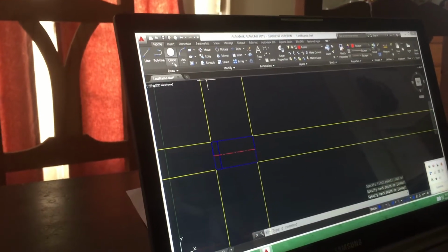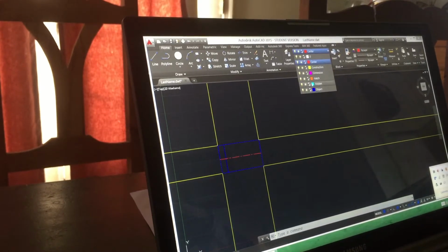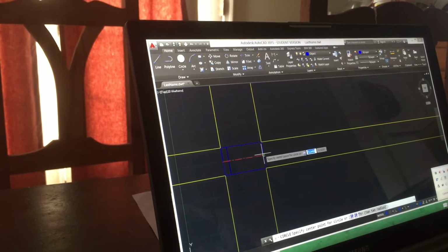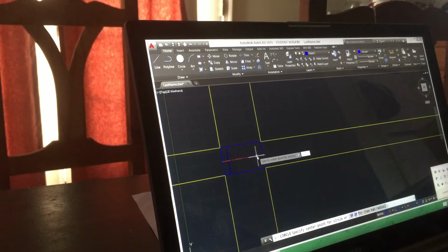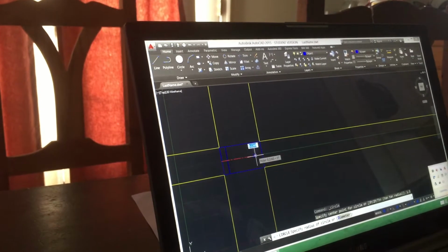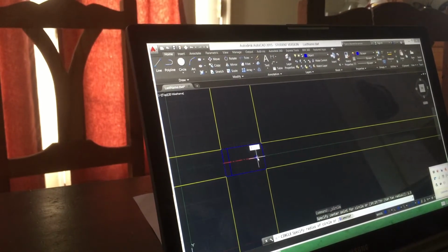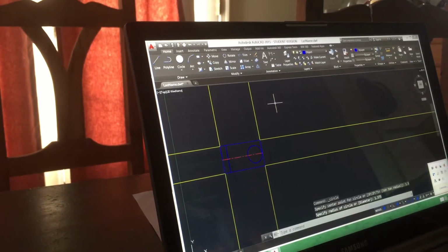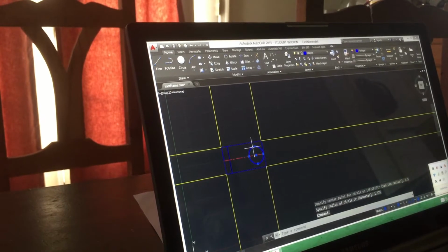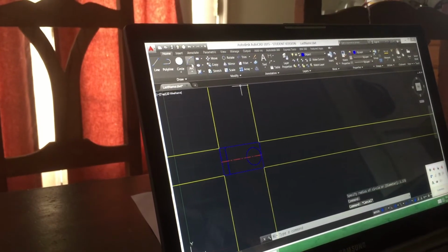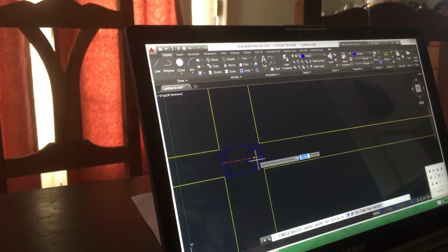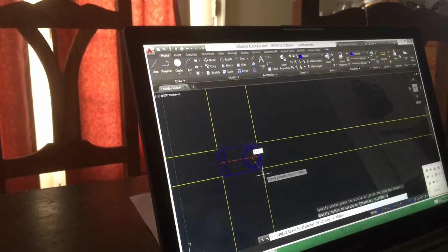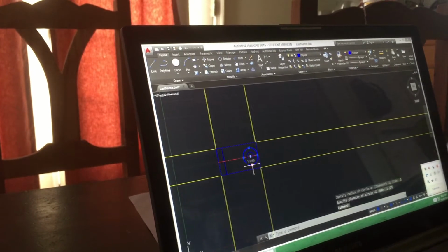And our first circle, change it back to object view. Our first circle is in 1.5 inches. And the diameter is 1 3/8, which is 1.375. But that should be the diameter, not the radius. So since I already have my center mark, I'll do another circle from there. This time I'll change it to diameter 1.375. And then I can just get rid of that one.